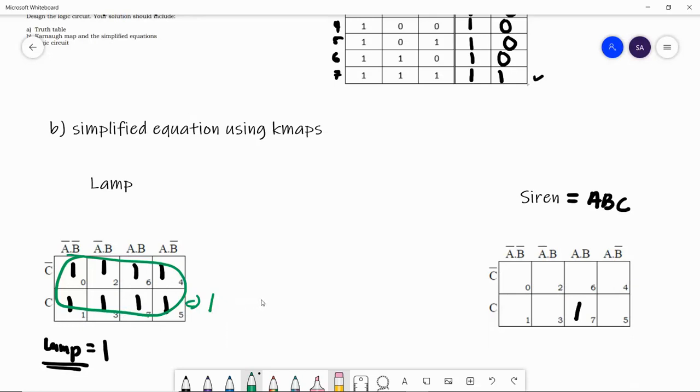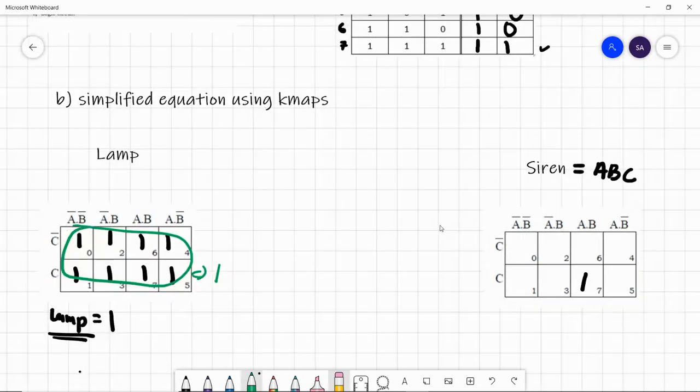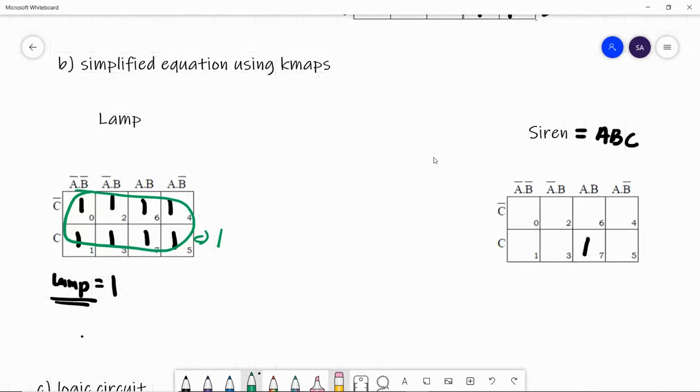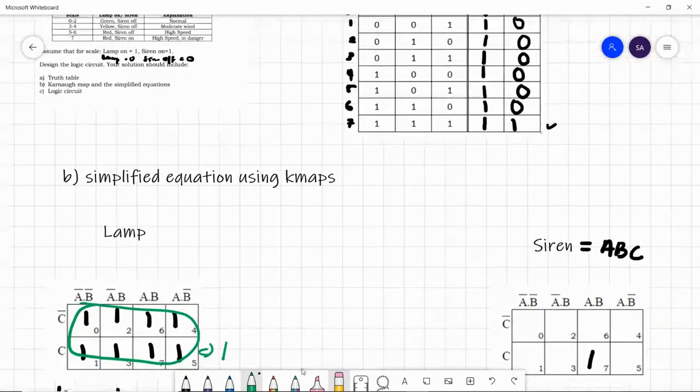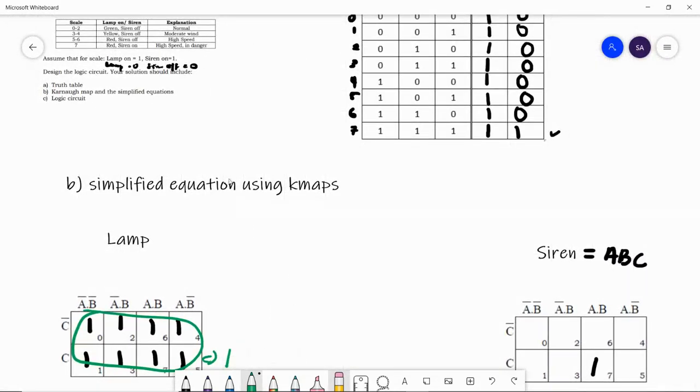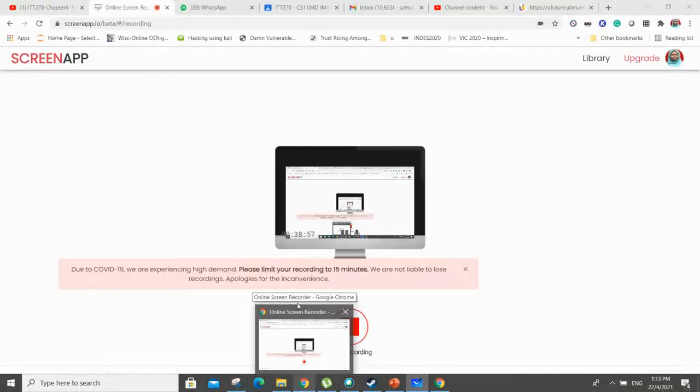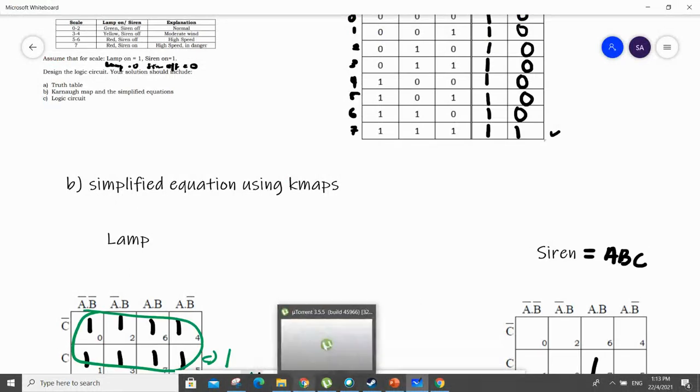After that, from that particular output, if there are 4 outputs, you need to make 4 K-maps. If there are 5 outputs, you make 5 K-maps, and then get each output's expression, and after that you draw the logic circuit diagram. This is a simple question. Alright, so that's all, because this is an example of how we combine materials of logic circuit diagram using K-maps.